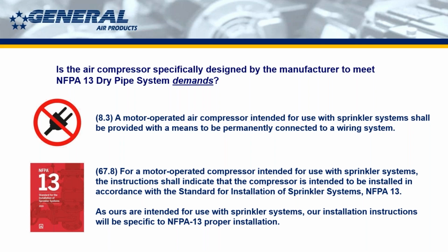And that's important. It's a really good thing to do. You don't have multiple things on that circuit. People aren't shutting the light off and accidentally shutting off the air compressor. This is a really good move by the standard, and it's something that people need to be aware of. So no more plug-in air compressors.